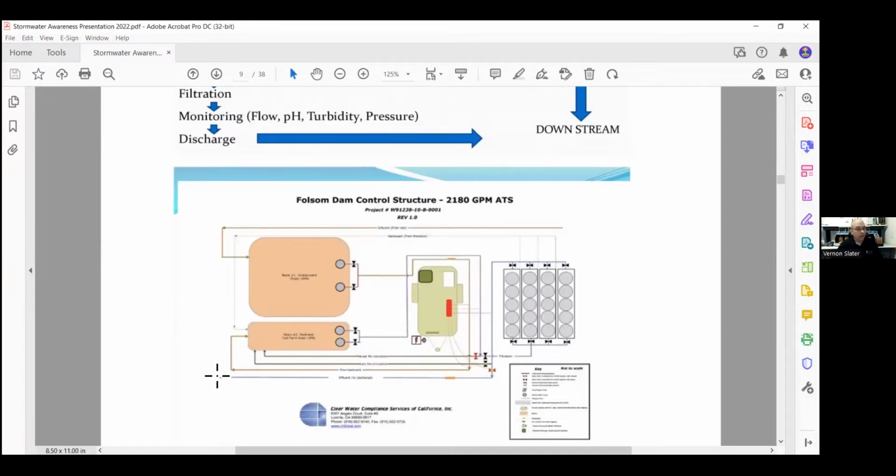An active treatment system protects natural waterways from the negative consequences of construction, land disturbances, or other man-made water quality problems. The active treatment system is the BMP of last resort, used when traditional BMPs may not control the accelerated release of sediment from erosion caused during rain events, and used where highly erosive soils are present, long steep slopes, clay or colloidal clays are present, and on large sites where the sheer volume of water capture cannot be released without violating numeric action limits or numeric effluent limitations.